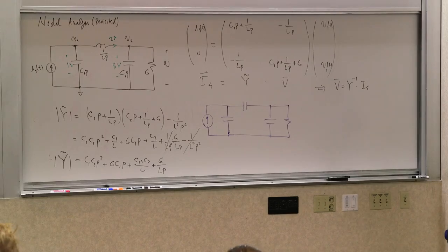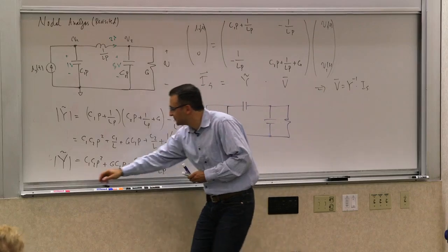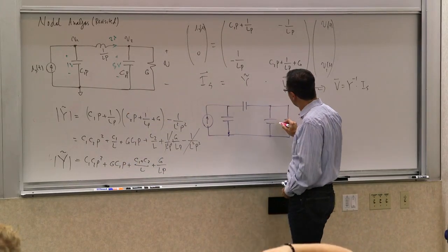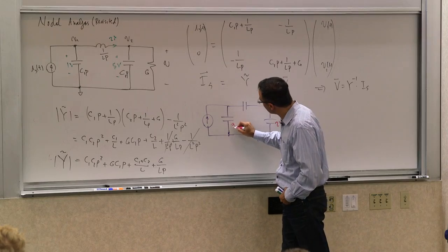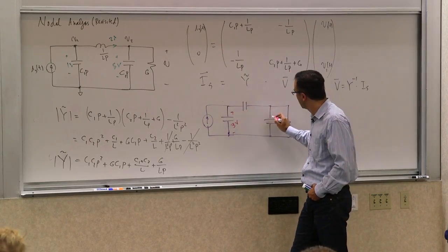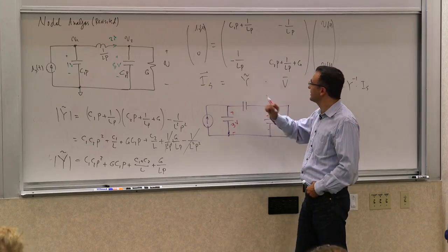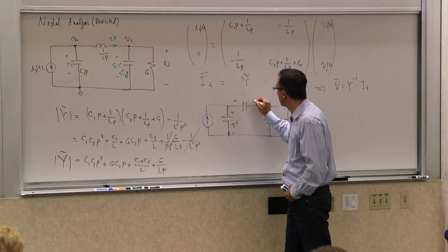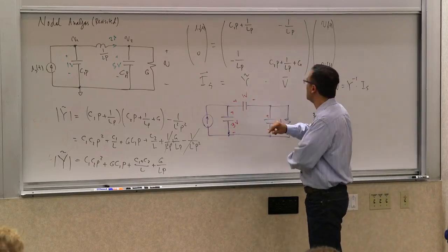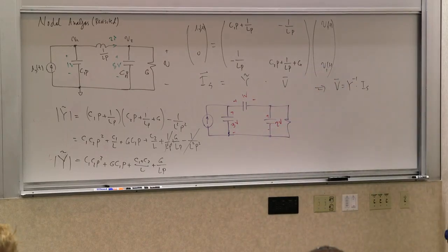Why? The voltage over the right capacitor and the voltage over the other. So let's say if I set this to 2 volts and if I set this to 3 volts, can I set this to any arbitrary voltage that I want? No, right? What is the voltage? 1 volt, exactly. So what you noticed is correct in the sense that if you had 3 capacitors in a loop, you will run into that trouble.